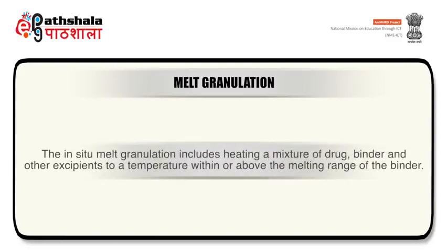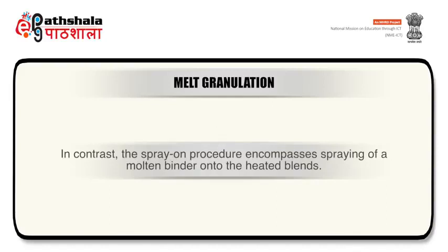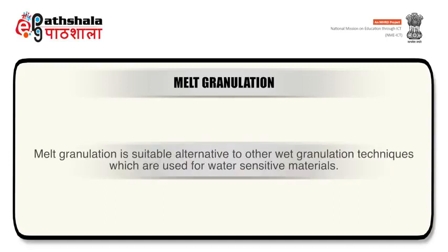The in situ melt granulation includes heating a mixture of drug, binder and other excipients to a temperature within or above the melting range of the binder. In contrast, the spray-on procedure encompasses spraying of a molten binder onto the heated blades. Melt granulation is a suitable alternative to other wet granulation techniques for water-sensitive materials.